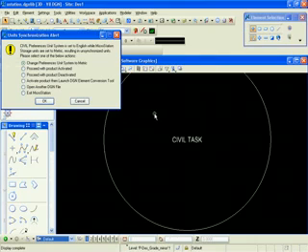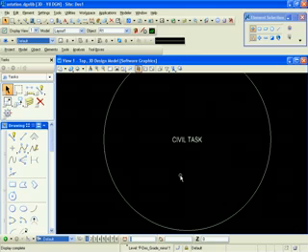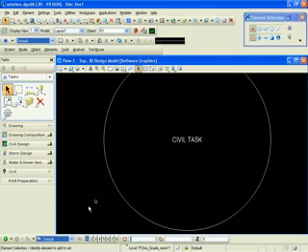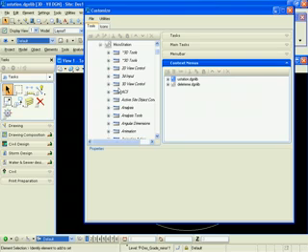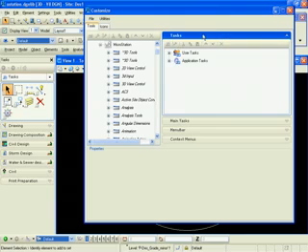I'm going to allow the Site Modeler project to be read-only, and I want to open up my Civil Task Menu DGN library. Under Workspace Customize, my menu will open, and I have tools on the left that I can add into my tasks. So you see we have tasks, main tasks, a menu bar, and context menus. First we need to know what each of these are.